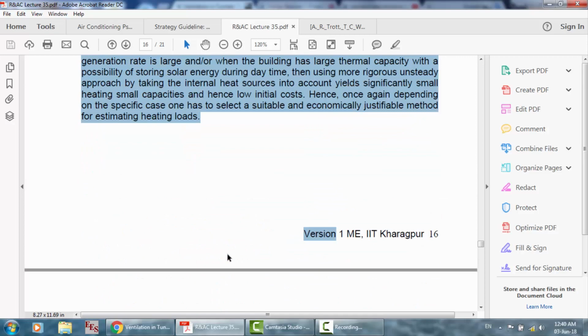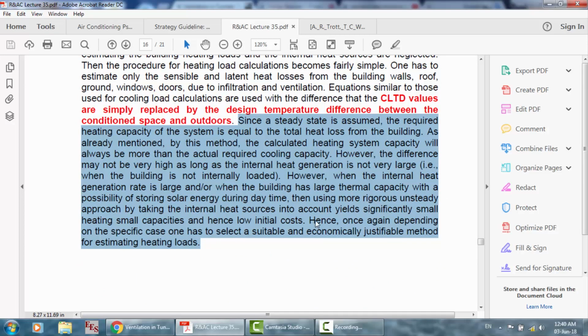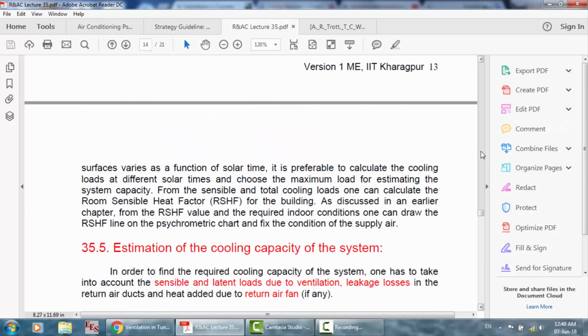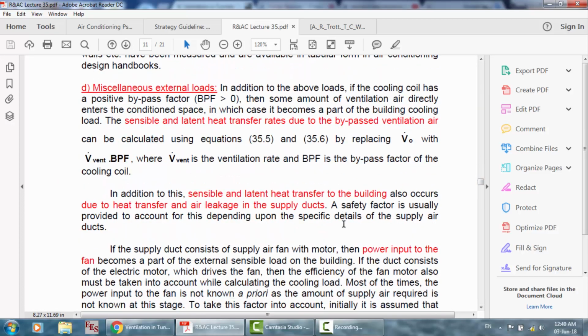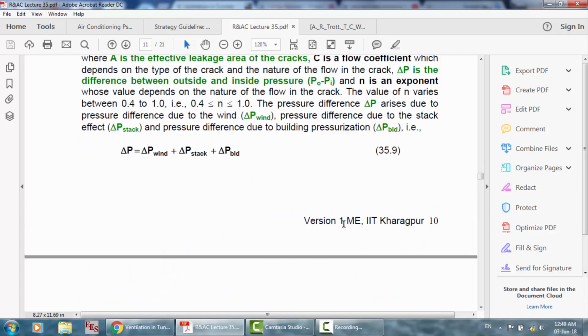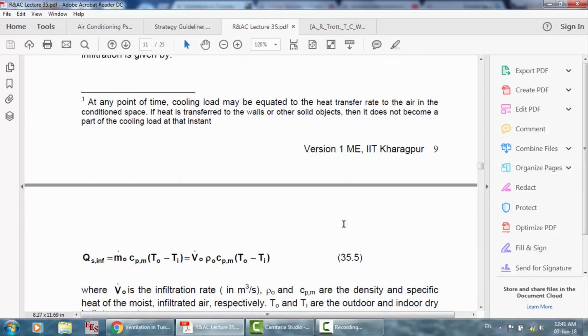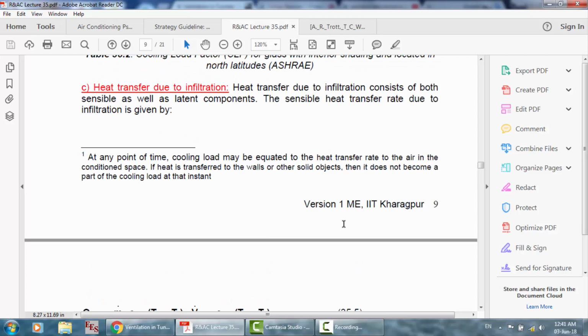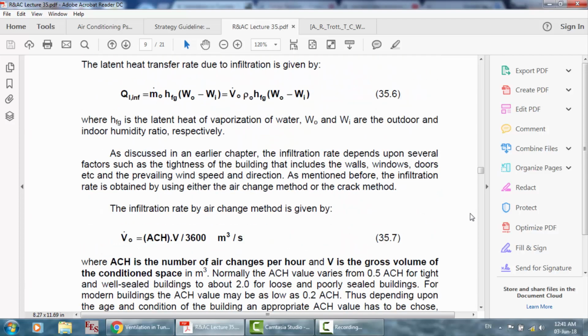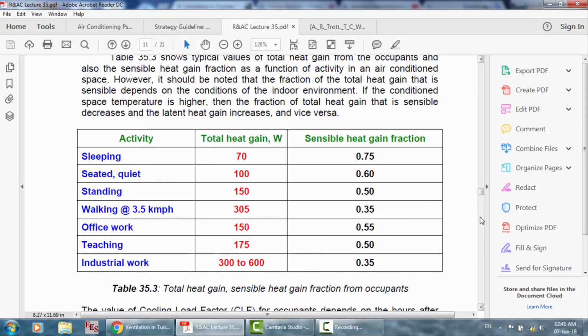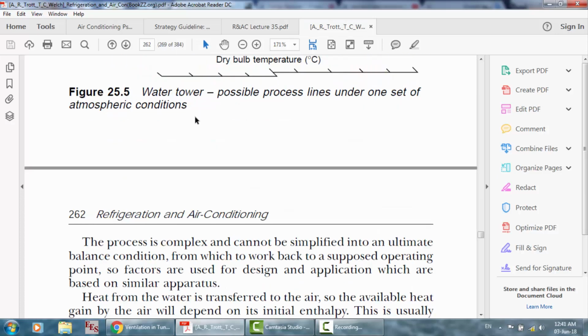So, gentlemen, you will follow the same procedure here, all these equations, but notice that the internal loads, heat from the appliances, people, and lighting will help you. If you calculate them, they will help you to decrease the heating load. Why? Because they add heat. Okay. So the same procedure, and no problem with this.